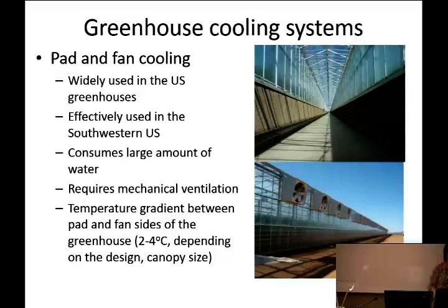All right, yes, Courtney. What is that top picture showing? Oh, the top picture. This is what we call the cooling corridor, the cooling walkway of the commercial greenhouse. So both sides are wet pad, and the air intake is at the top of the roof. It's like two-thirds of this classroom width, just one bay of greenhouse.